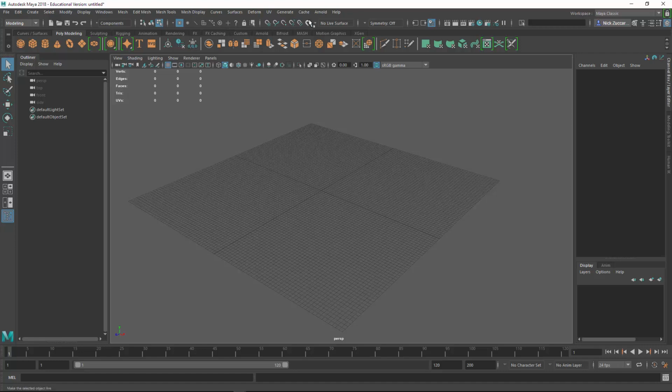But we also have verbiage down in the bottom left-hand corner that might tell you something about these things as well. So we've got something like snap to grid, we can snap to curves, we can snap to points, this is snap to projected center, snap to view planes, and then this is making something live. That's kind of interesting, where you can take an object and make it live, and it becomes almost like a sticky surface where anything that you make new will actually stick to that surface. So that's actually pretty cool.